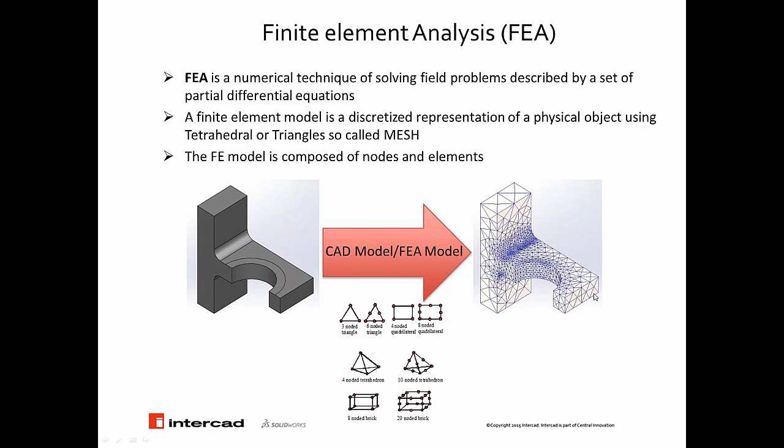For that purpose, you need an element, which could be a triangular shape, or brick shape, or tetrahedral shape, or any other shape with some nodes on it, and you put a series or network of those elements onto your CAD geometry and represent your CAD geometry with that network.